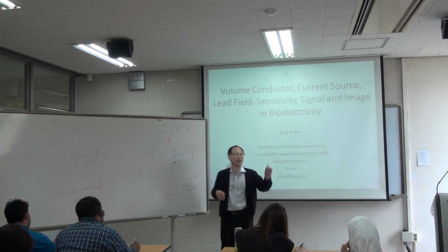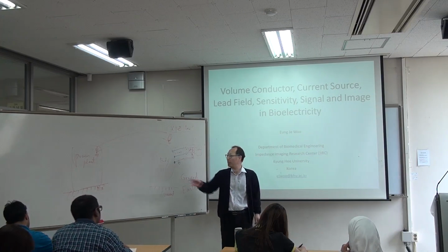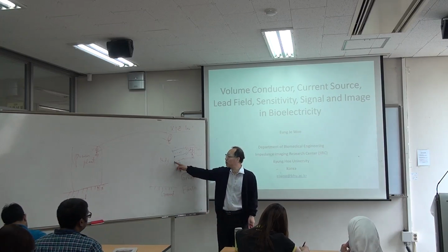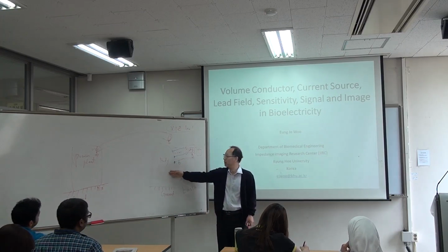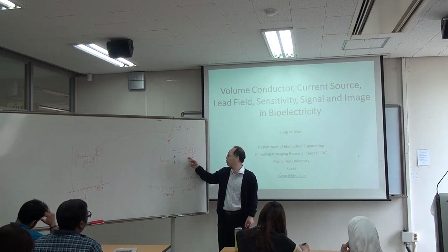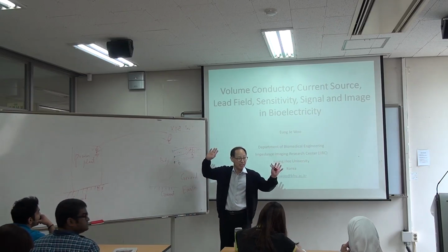So back to your question. How do you connect the body to the ground? We just put an electrode on any part of the body and then connect that electrode to the circuit voltage reference point. That's it.